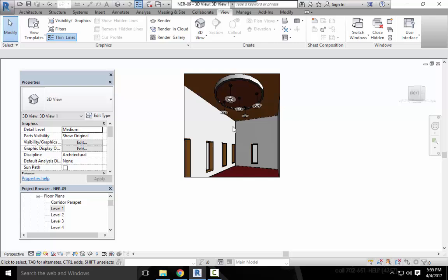But it walked you through the steps of how to create multiple ceilings, create soffit walls, add lighting fixtures. We actually walked through a significant amount of ceiling stuff. Really, we walked through all the ceiling stuff that the book is going to talk about in detail. We may add some ceilings later in the process, but now you should be able to add ceilings, whether they're bounded by rooms or not bounded by rooms. You can go to sketch mode. You can change them almost any way you want.